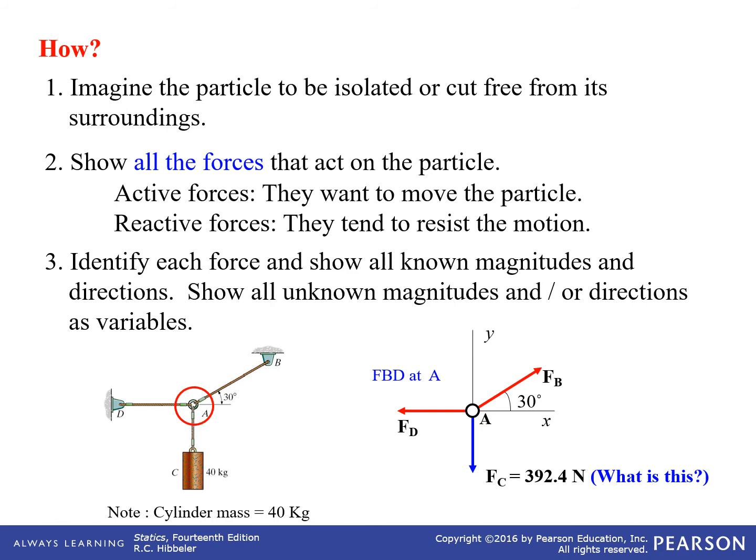The directions are important, and the angles that are given in a particular problem are what's important. Now, one note on the XY plane: you can specify your XYZ in any direction you choose. Usually you want to apply it where it makes the most sense. The way they've applied it here, you notice that FC only acts in the Y direction and FD only acts in the X direction. So the only one that has an X and a Y component is FB, which makes it a little bit easier.